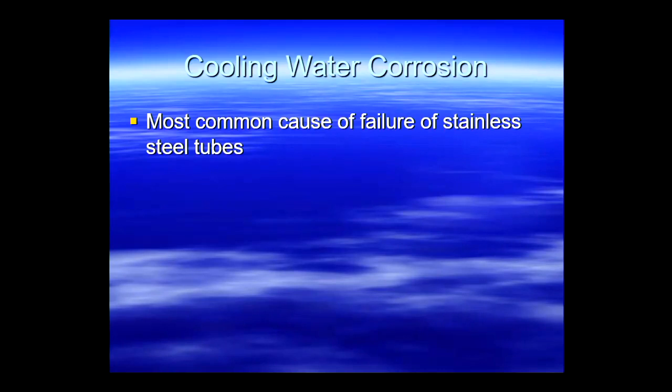If you don't do that, the water goes black within a few days with all sorts of bugs inhabiting this wonderful warm atmosphere full of all sorts of stuff, and it becomes extremely dangerous. And if you don't treat it with a biocide, you end up breeding cholera and typhoid and heaven knows what else. So they're the three things you have to do to cooling water. There are very tight specs associated with each of them, so the plant works.